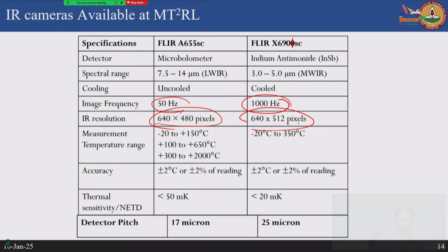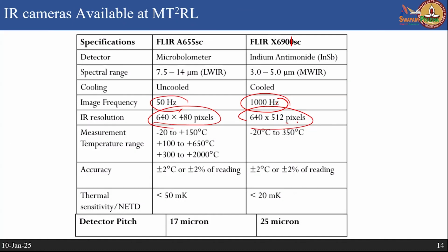Okay. So there is no new jargon there, and even the quality of the detectors depends on the temperature range that you want to measure. For example, if your detector is chosen for this temperature range, you cannot use it for a higher temperature range. This one is only capable of detecting minus 20 degrees to plus 350 degrees.